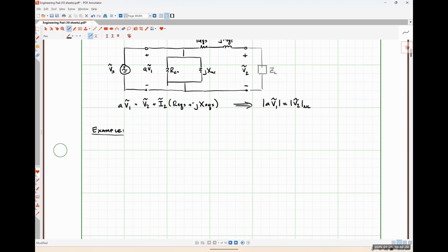I think, okay. So this concept of voltage regulation is effectively about how good of a job the secondary does at maintaining its terminal voltage or its nominal voltage under various loading conditions. Okay, that's really all this is. So for a distribution transformer, we would want that voltage regulation to be rather small, because we don't want that voltage to change a whole lot when a bunch of people, let's say, turn on their ovens at the same time because they need to cook dinner, right? Most people get off work about 5, maybe they start cooking dinner around 6.